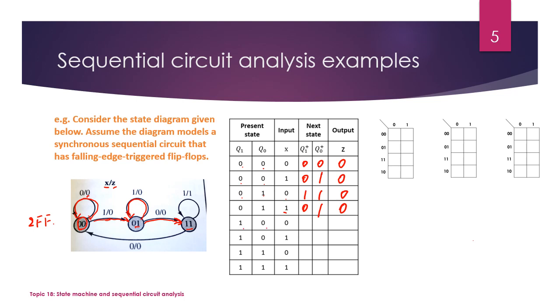however, this state is not showing in this machine, right? It's not there. So how do we deal with that? Basically, it's not there, which means first, we don't know its value, and also we don't care about its value because it's not inside the loop. No matter what value we put here, it shouldn't affect this machine. So the next state is actually don't know or don't care, and we don't know the Z value either.